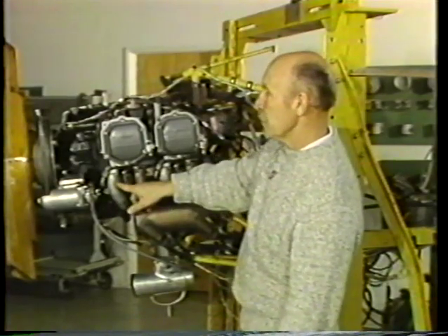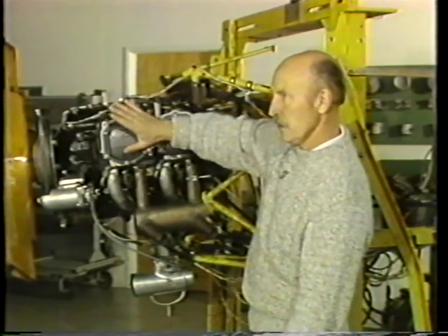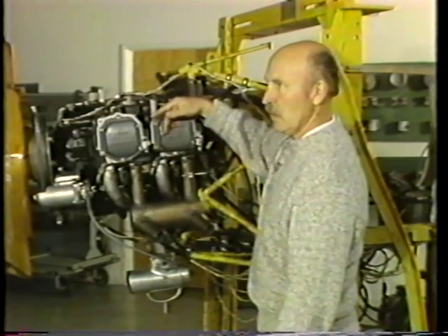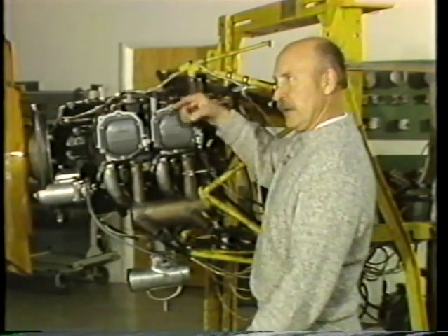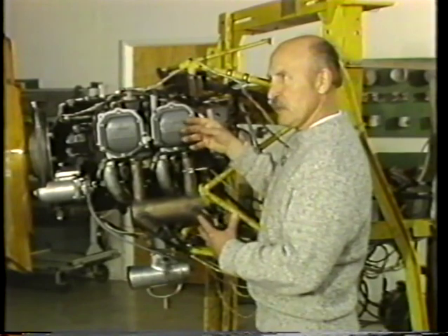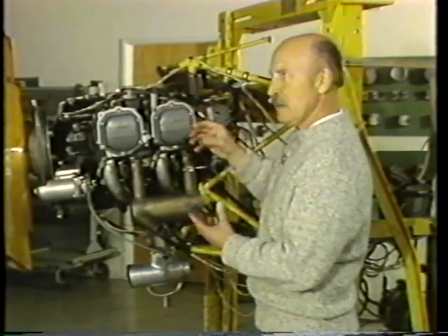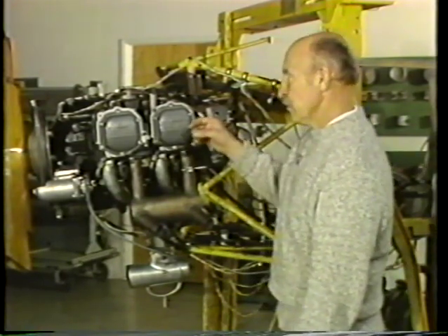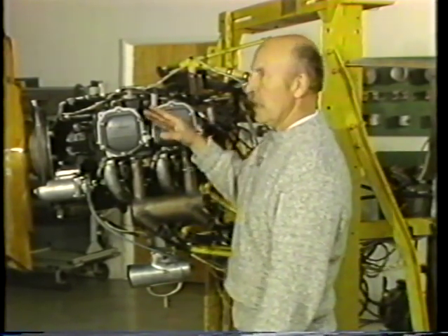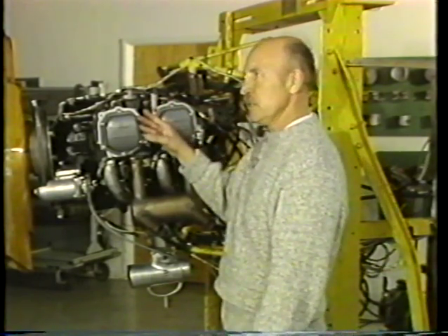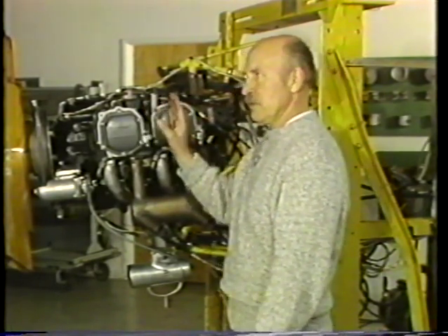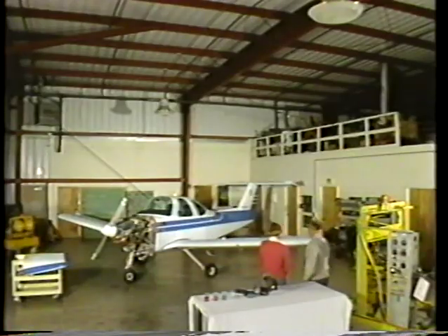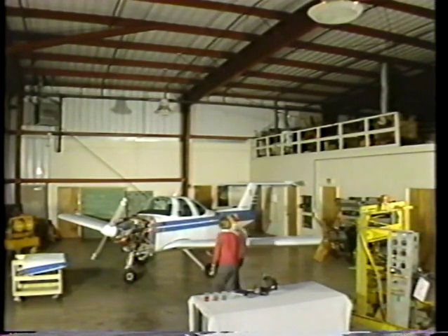Now the air comes in through here. When the intake valve opens, the fuel-air mixture is forced into the cylinder. And since we don't mix the fuel and air in the carburetor, here we have the fuel control unit that simply measures them. We eliminate that problem of the carburetor where the temperature drop occurs and icing would occur. The problem that is possible to run into with any carburetor or fuel injection system is impact icing, when we have structural icing on the aircraft flying through freezing rain and that type of thing. Let's go over to the Skipper, Jeannie, and I'll show you how the ignition system works.